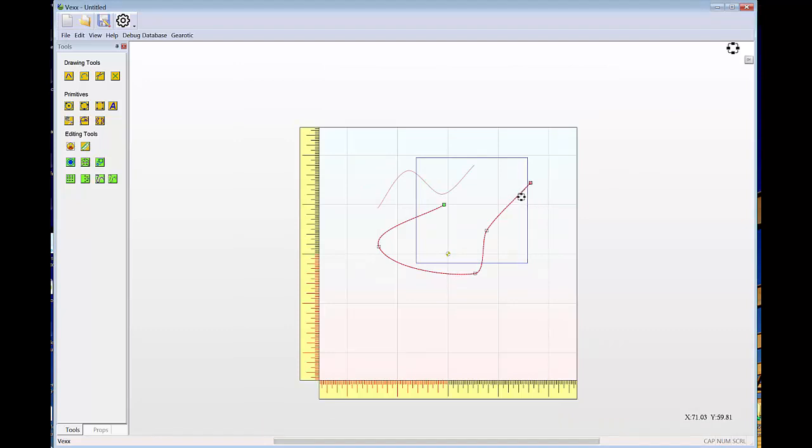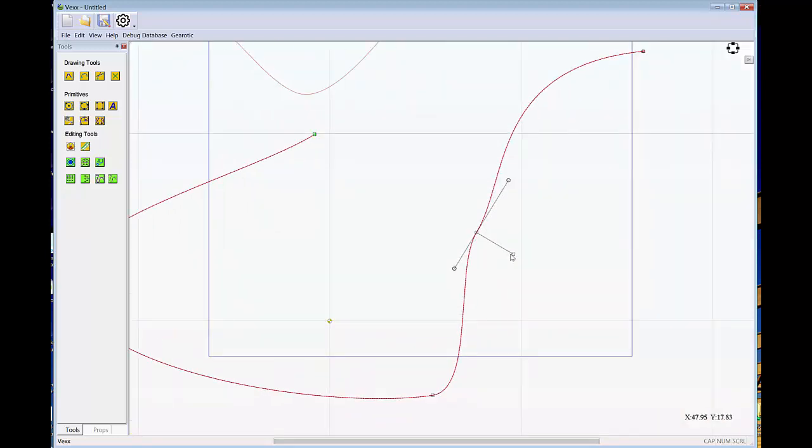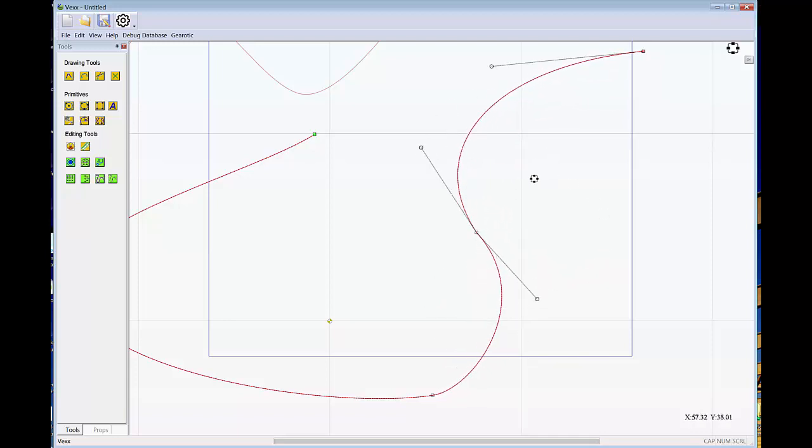Now, Bezier curves, when selected, have control handles that you can use to adjust your curves. In the case of a mid-node, it has three handles. One handle will move a tangent on one side, the top handle will control the tangent on the other side, and the middle handle, by pushing in and out and bending, will control both tangents to keep things in a more continuous curvature, in case you're editing something and you want to maintain a curvature across various control points.